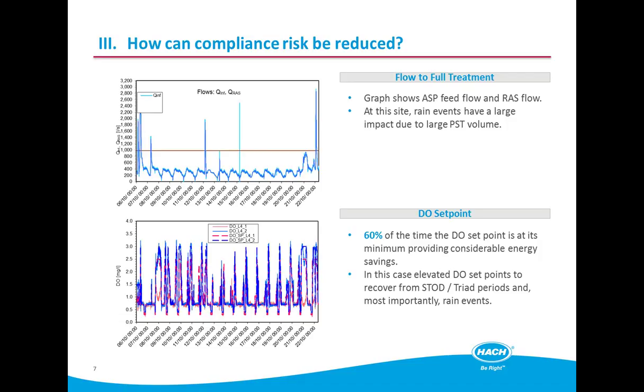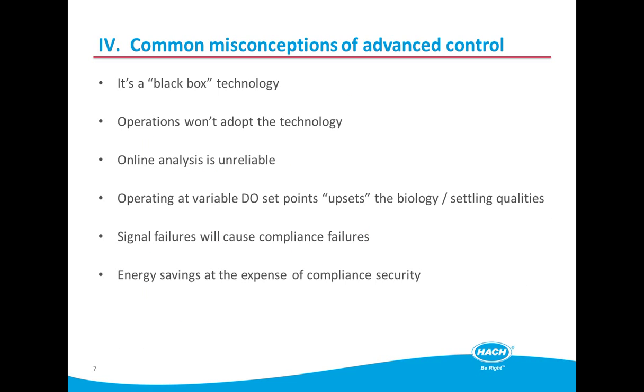Without that response, a final effluent ammonia spike would have resulted, but instead, the plant automatically responded and delivered the right level of treatment. So the nitrification system has been fully developed and implemented and is successfully operating in the UK, Europe and in the USA. But there are still misunderstandings within the water industry about real-time control.